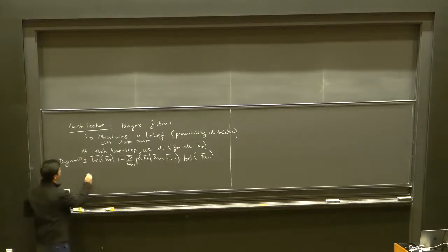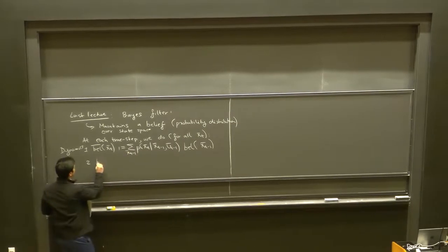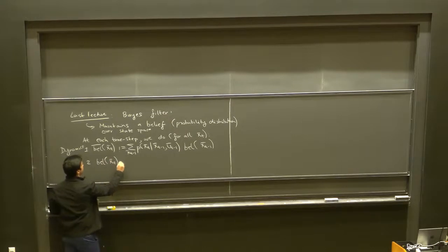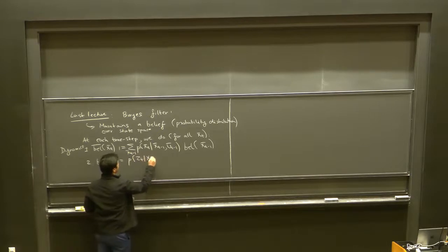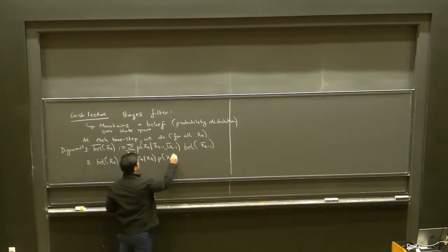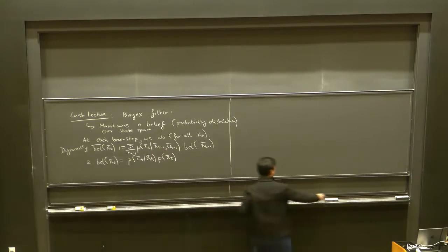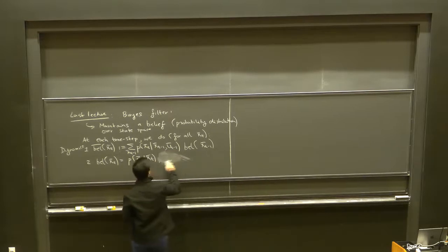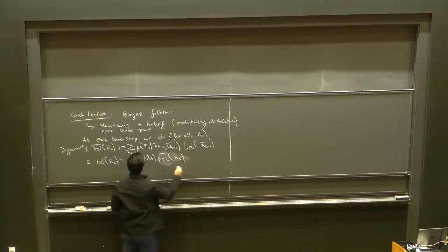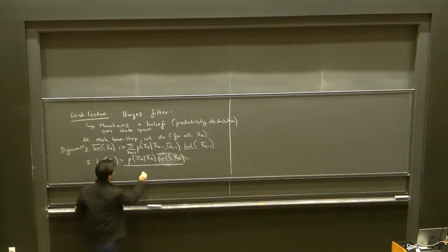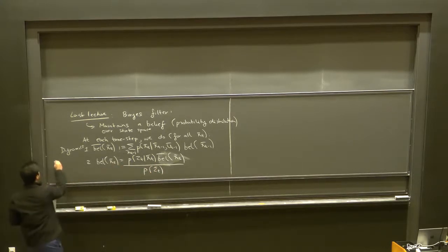And the second step is to take into account the new sensor measurement that the robot receives and update your belief using that. And that's where Bayes rule comes in. Sorry, there should be a belief bar, divided by P of zt. And this is the measurement update.